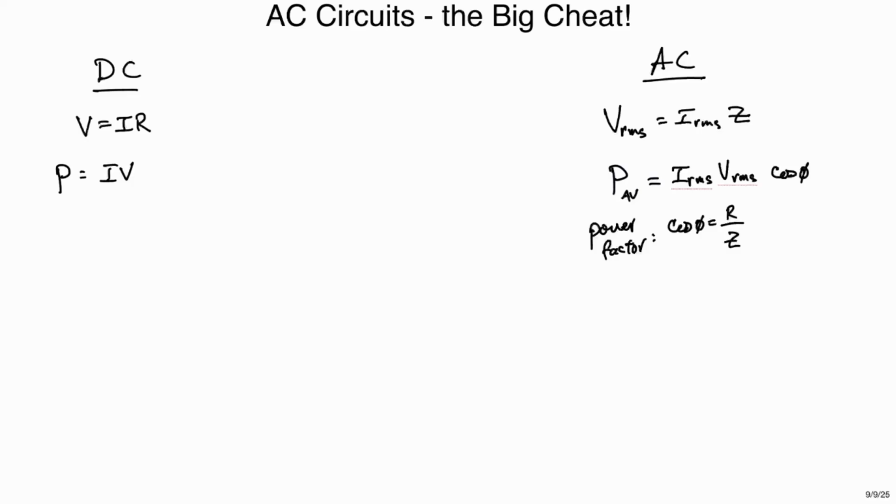One thing you need to understand about RMS, root mean square, is that there's a difference between this root mean square, which is like an average, and the maximum voltage or current that could be happening anywhere in the circuit. The conversion between the absolute most you could have and the time average is a square root of 2. And this applies to the current as well.